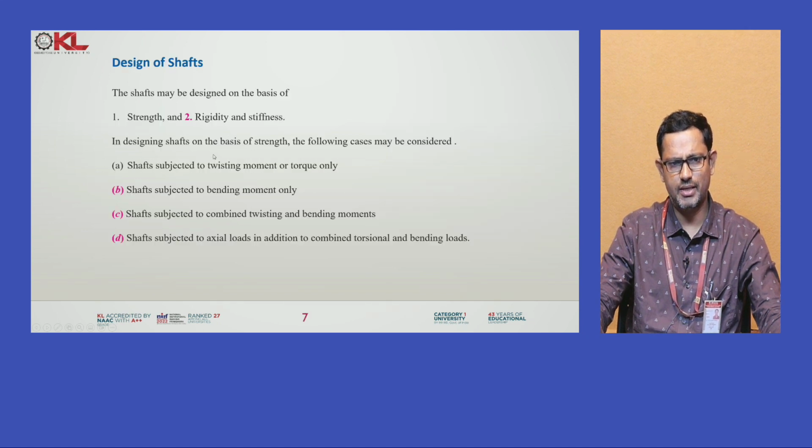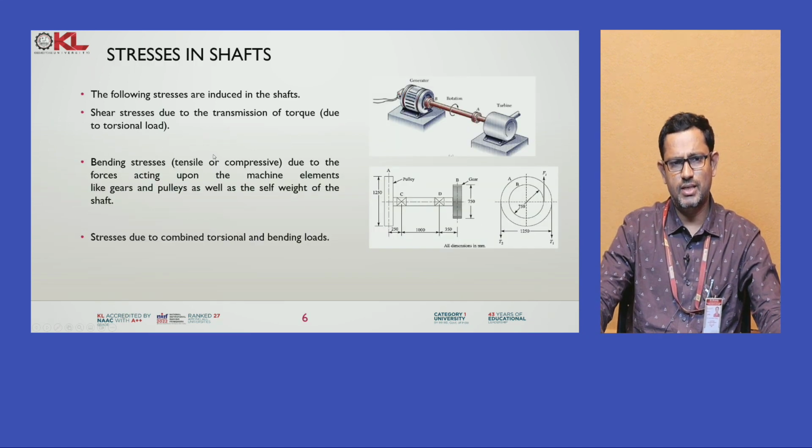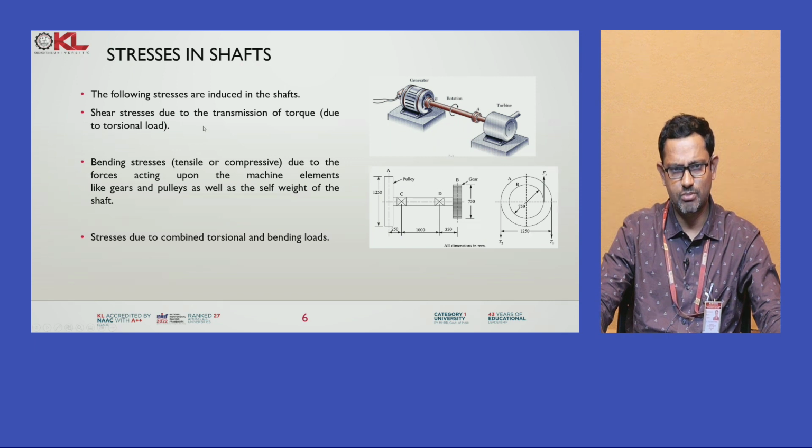Our topic here is the design of shafts subjected to twisting moment and bending moment. So let's consider when the shaft will be subjected to the twisting moment, that means shear stresses, because we know that shafts are majorly used to transmit power from driver to the driven member. Because of this transmission of torque, the shafts will be subjected to shear stresses.